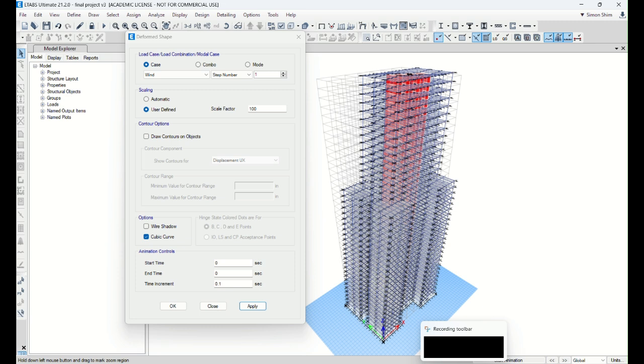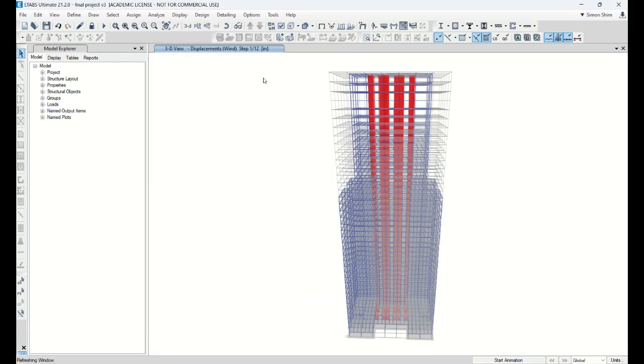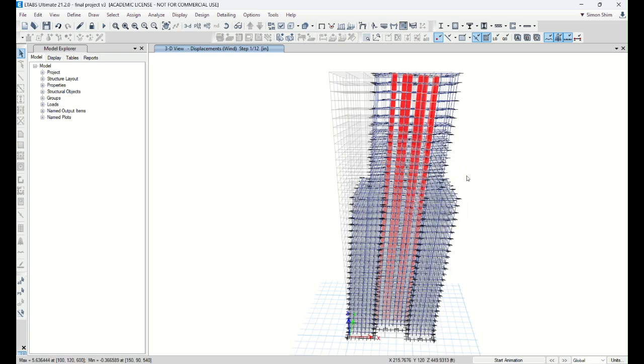Do you see that? Sometimes you make a mistake, some column maybe discontinued, and beam and column are just dancing, right? You should be able to check connectivity, right? So now you don't see anything, it's more global building performance movement, right? By just checking the deformations, the displacements, you could check X direction, Y direction. That's your validation procedure.